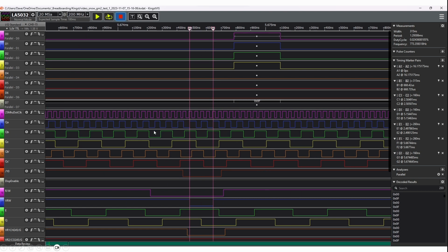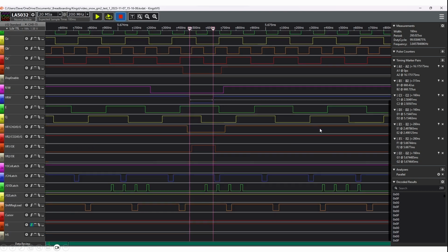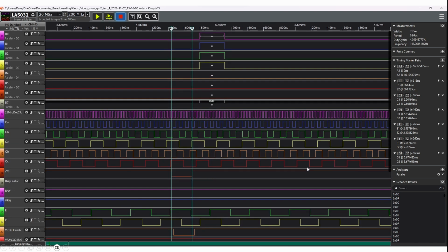And another couple of examples here. So you get the gist of things, that really where these various timing signals, in particular the Y0, are overlapping with this character latch here, tends to be the thing that's driving the interference. And there are just various scenarios.